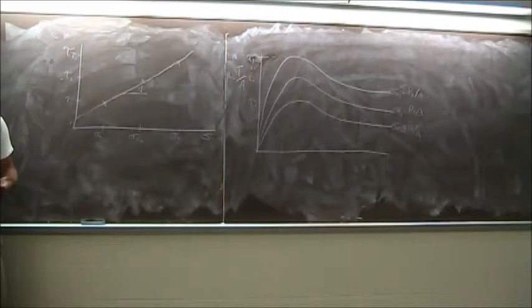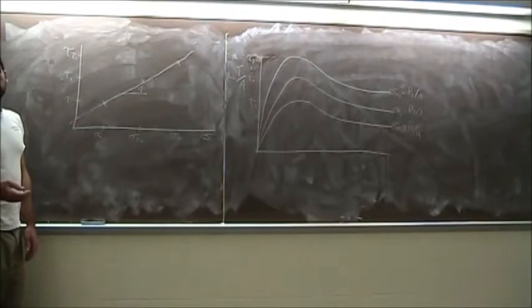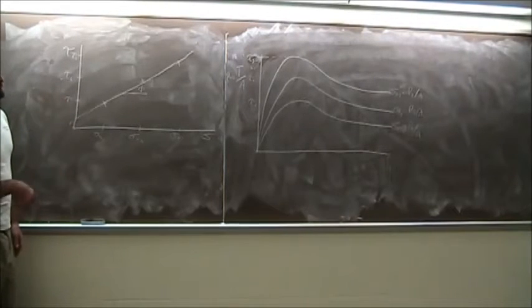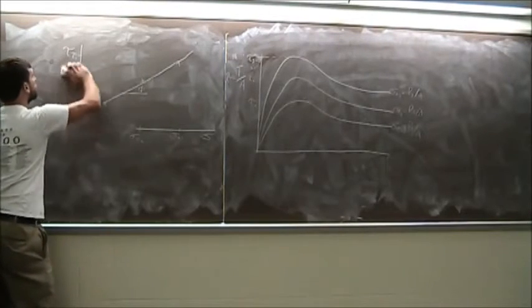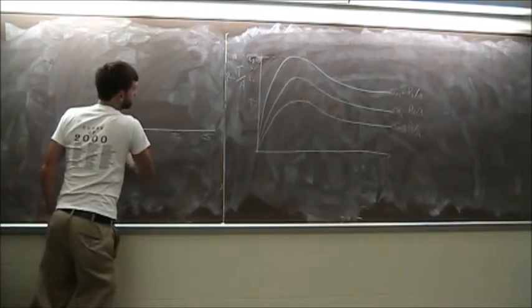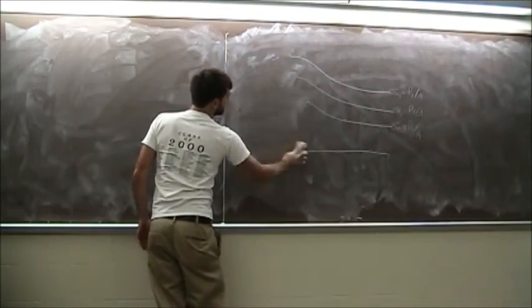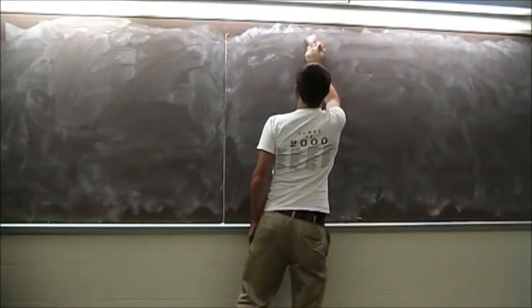Okay. Yeah, actually that's about it for the data reduction of this type of test. So that's what you do. You run different tests, and you run them at different normal stress levels, and that way you can determine how the shear stress varies with normal stress and figure out your failure envelope. But I talked earlier about how we also measure the vertical deformation, and I'm going to show you how that plots up and talk about how soils respond